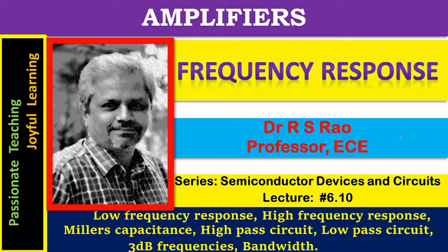In practice, this gain parameter depends upon the frequency of the signal. At the lower frequencies, the gain decreases with the decrease in signal frequency, and at higher frequencies the gain decreases with increase in frequency, and in the middle the gain remains somewhat stable, varying very little with frequency. Gain dependence on frequency is a drawback, a shortcoming. It has to be arrested. It has to be removed.